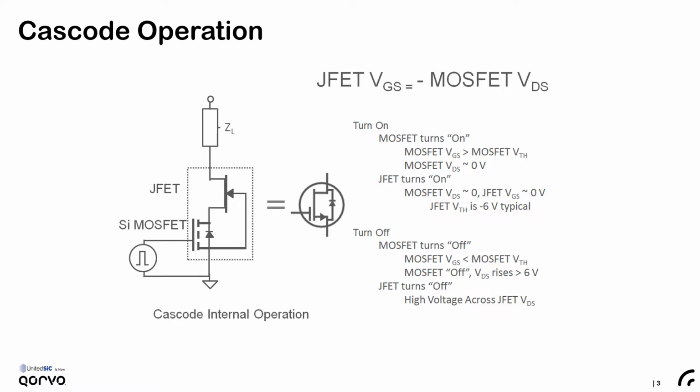Silicon carbide FET is formed by a high-voltage silicon carbide JFET and a low-voltage silicon MOSFET in a cascode structure to deliver normally off behavior. The high-voltage silicon carbide JFET is a normally on device that requires negative gate-to-source voltage to turn off. The low-voltage silicon MOSFET drain-to-source voltage serves as the gate drive to turn on and turn off the JFET.